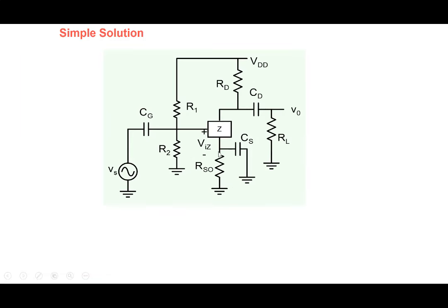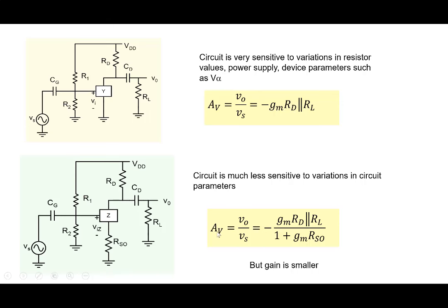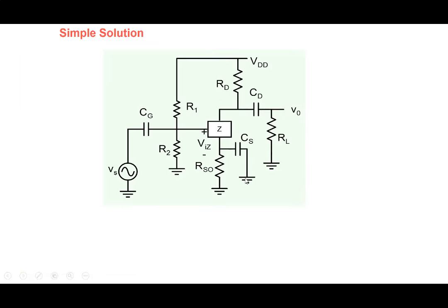But that's fairly easy to solve. Note that the gain we are talking about is an AC gain, depending on the AC input here. And this term is arising because there's a resistor Rs0 here. So if we connect a capacitor across it, then under AC condition, if the capacitor value is large, this 1 by omega Cs will come in parallel with Rs0.